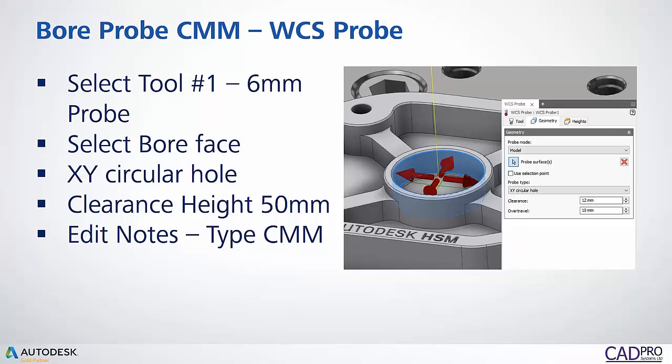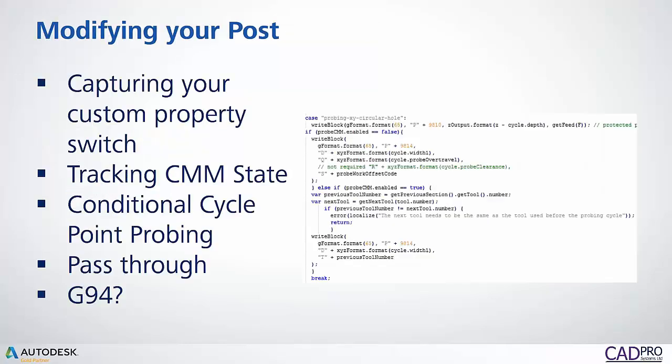But naturally, you can't measure with the same tool it's cutting and expect that somehow it's more accurate in its positioning with a probe versus a tool. What this is going to do is catch inaccuracies in the tool or deflection or something like that. I'll jump in and say that there's definitely the question of measuring it with the tool that you made it with, and there's no replacement for offline inspection, but you can mitigate some.